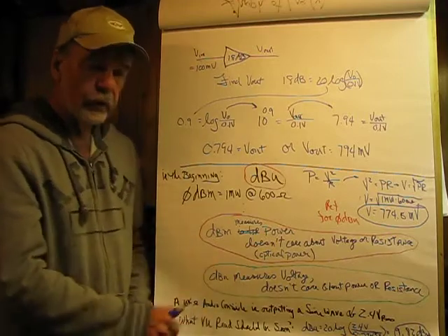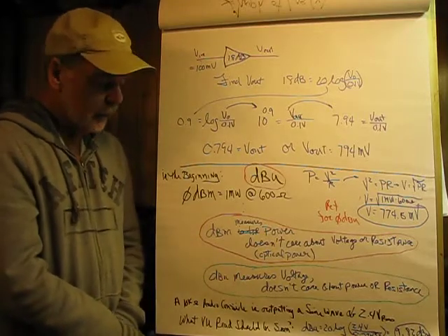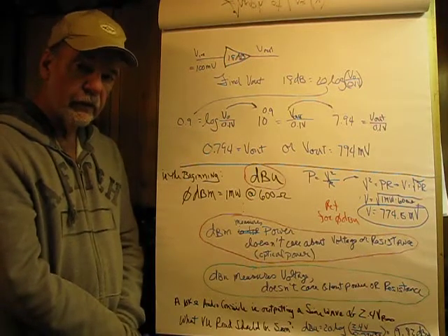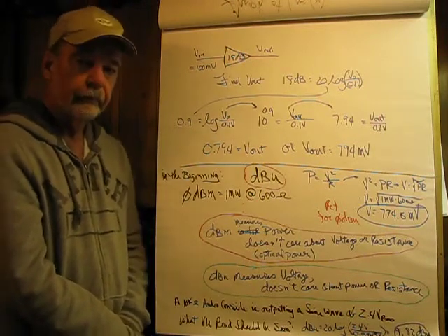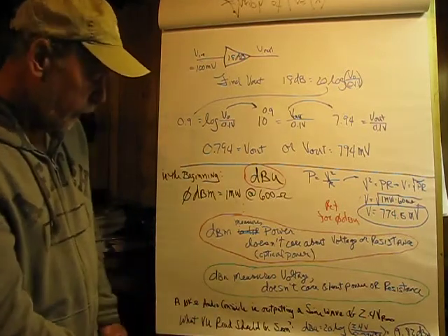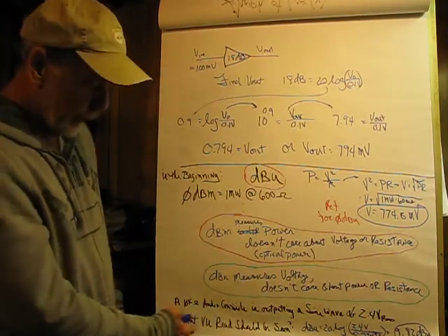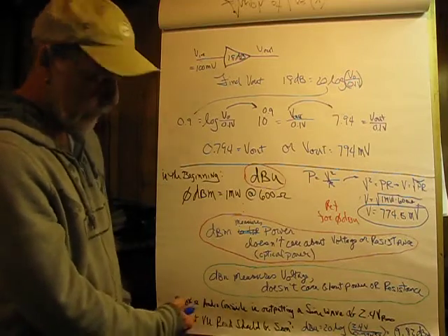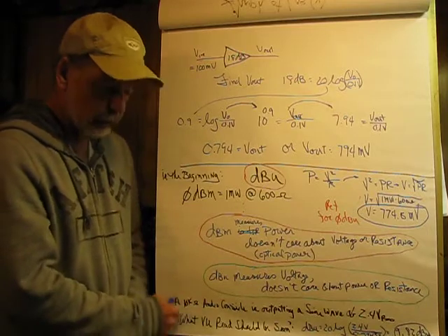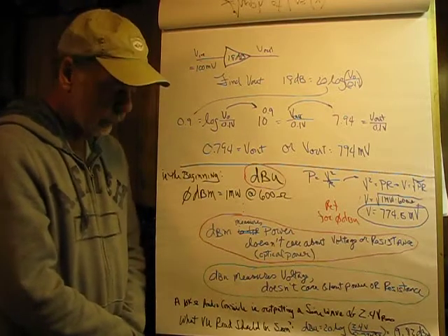Likewise, dBu is all about voltage. A typical audio system runs at a 10K impedance. Doesn't matter what the power is. It's just about voltage. So, for example, if we had an audio console, and I have 10K here just to make the point, that would be the operating Z of most of the electronics in the audio console.